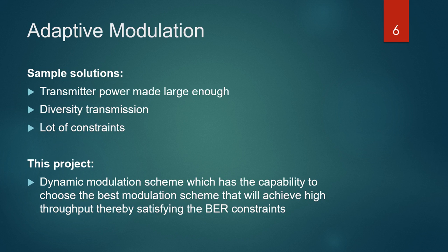Also another point to be noted is that for MQAM, the binary sequence of data is converted to gray coding representation in order to minimize the errors. In gray coding, the differences in values that are received at the receiver end cannot go through the states that are not a part of the gray code sequence for the given number of input bits. Thus, gray coding is an efficient and clever way of representation in order to minimize the probability of error.